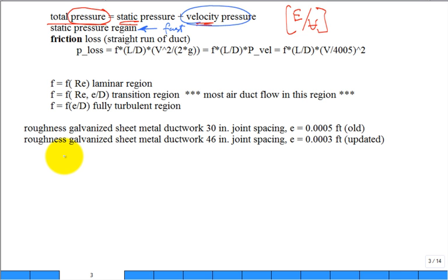When do you have a high velocity system? When you're far away from noise sensitive areas, or you can insulate it from the noise, and you just need to move a lot of air to get from here to there. So in this building, there's some main ducts that may go between floors that have some pretty high velocities.